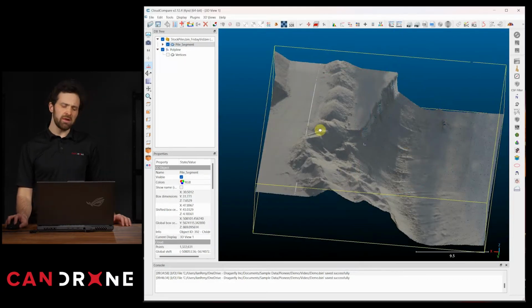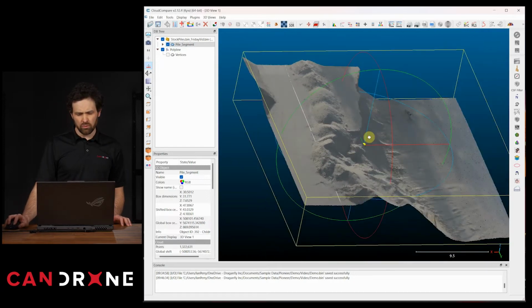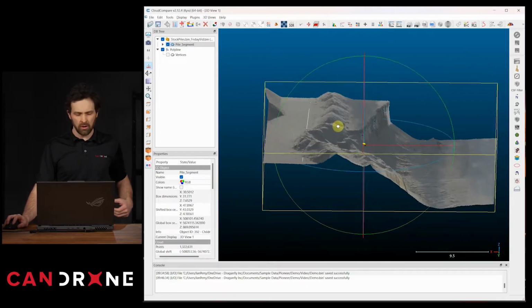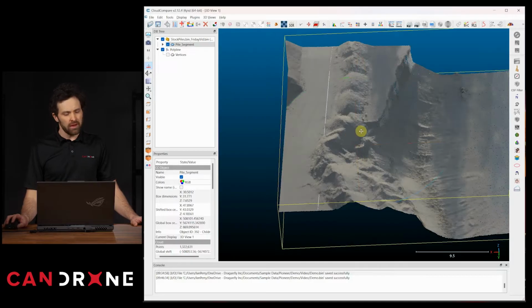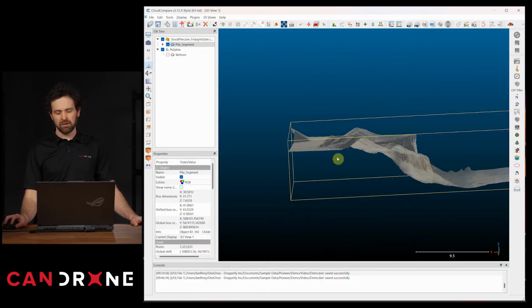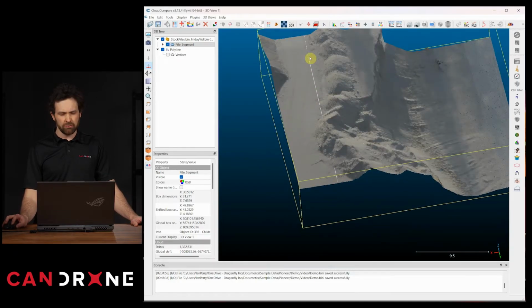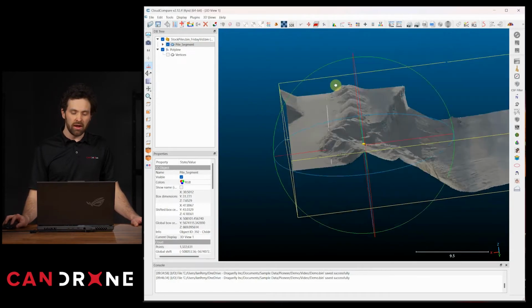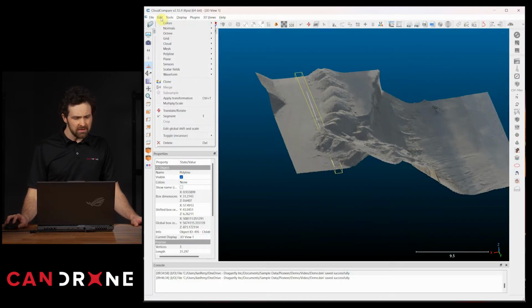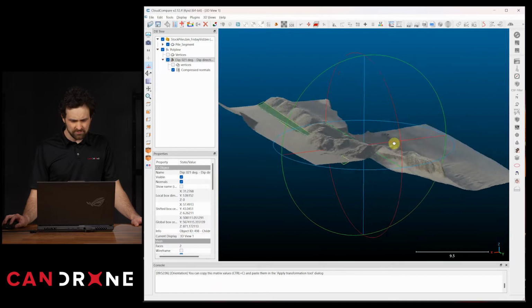Okay, so that just basically demarcates roughly where the edge of the road will be, where it will start to slope at 45 or 50 degrees down to the bottom of the quarry, all right? So now what's going to happen next is I'm going to want to create a plane at 45 or 50 degrees from that reference, from that polyline I just created. So I'm going to highlight the polyline and I'm going to go into Edit and I'm going to go to the option Plane and I'm going to simply Fit.